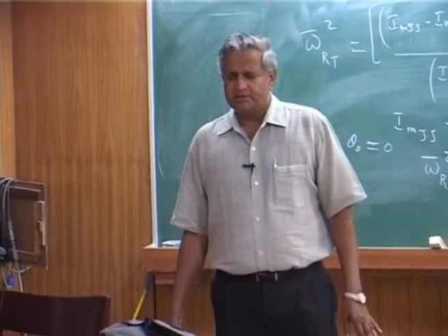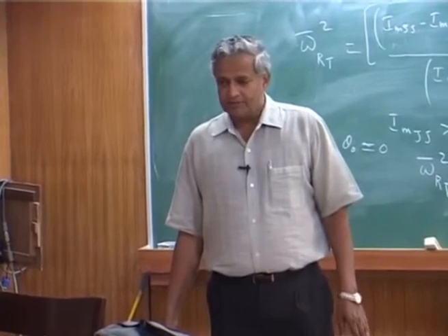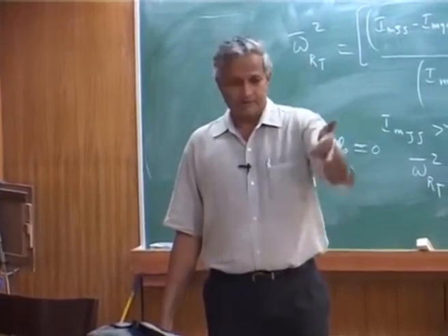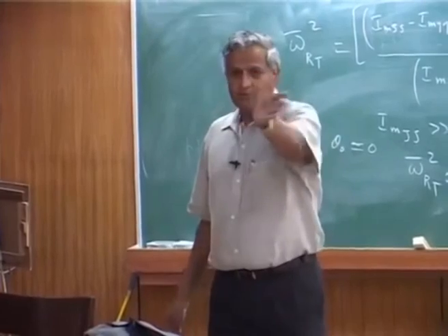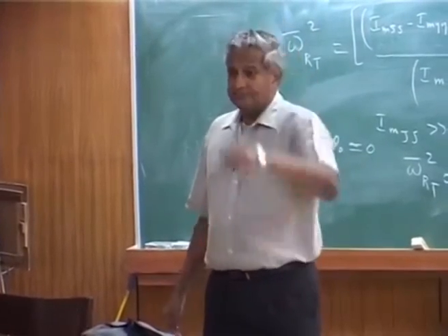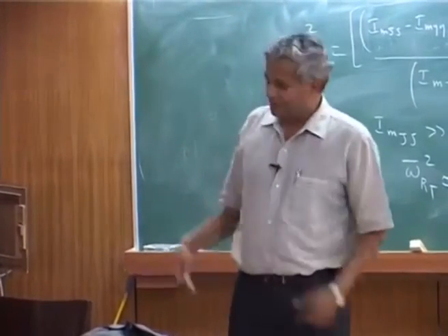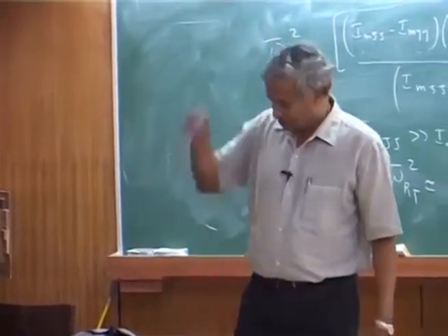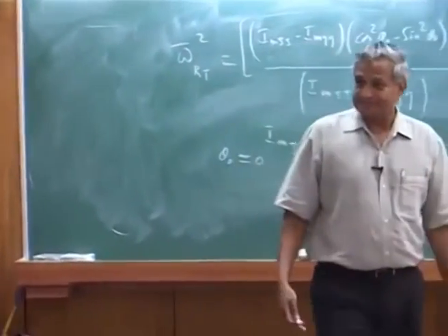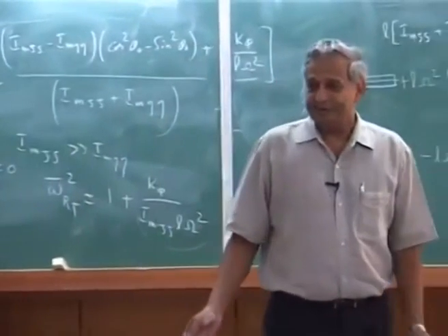Aerodynamic force. Aerodynamics of a static wing and a rotary wing have plenty of differences. First of all, the flow velocity is varying across the span. You will have a radial flow, and you have an inflow. Everything is there. Flow is in all directions.